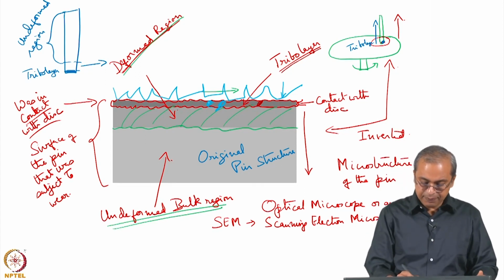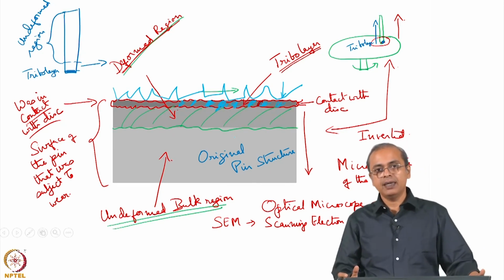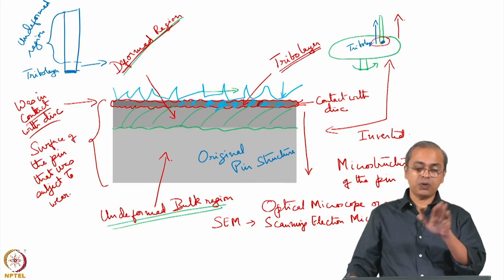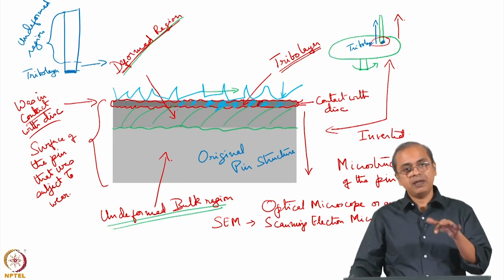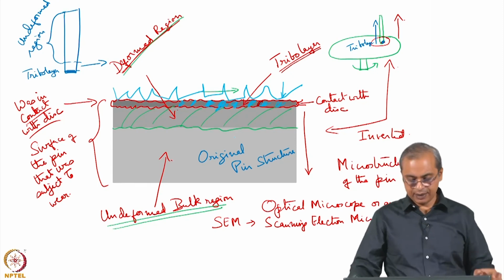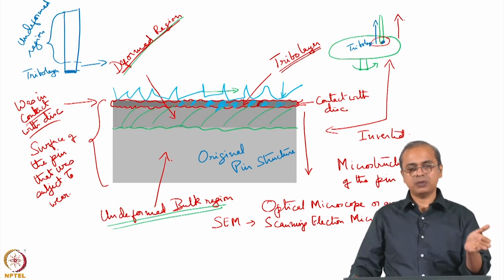But in addition, any debris that has been formed due to the wear is also participating and assisting this wear process. So, like I said, if you have an oxide layer and that oxide layer is protective, then it is helpful. But if the oxide layer breaks down and it also forms a hard particle that can actually impact the degradation process, then it is not helpful, it actually makes the situation worse.